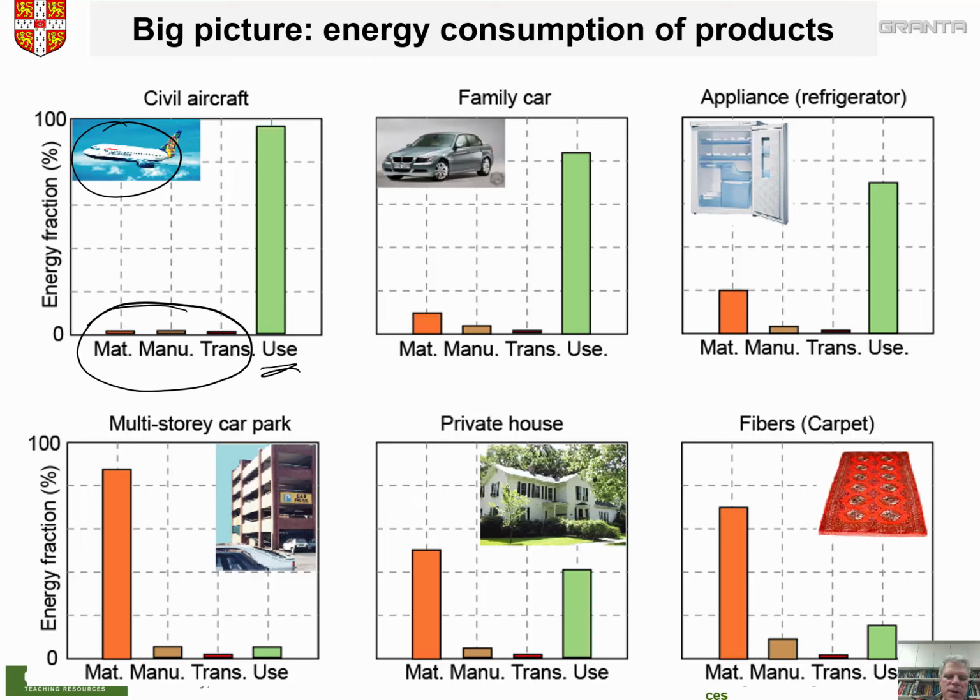If you're making an automobile, it's not quite as stark. The energy required to make the materials is important. Again, if you use something like aluminum, you're going to drive this up. You might drive down the amount in use, but under certain circumstances, it can be a wash. We can be quantitative about that. In a refrigerator, it burns a lot of energy during use. Most of the time, if you put a little more money in insulation, you can drive that down, but you might drive the amount of energy used in making materials up. So there are balances in these things.